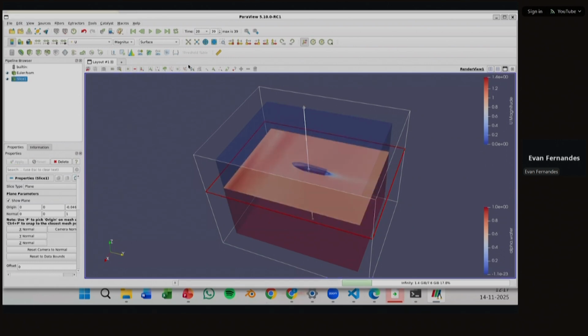If you run the simulation for a longer duration, you will see all of those contours that are there in the report. In our case, we've just run it for a short time, so we are not able to see that much of it. So this way you can post process. You can use a slice or you can use clip. There are multiple ways to do that.